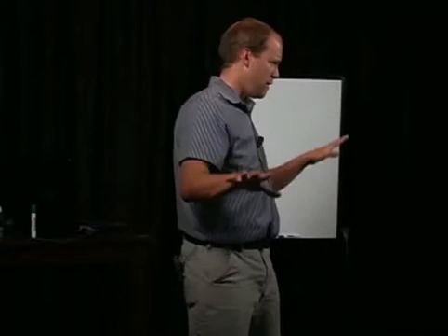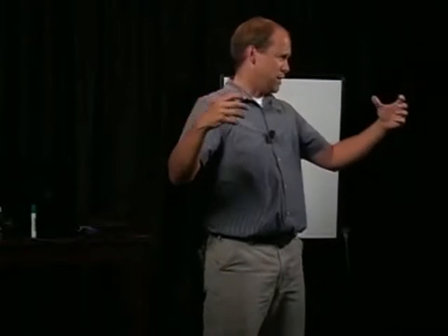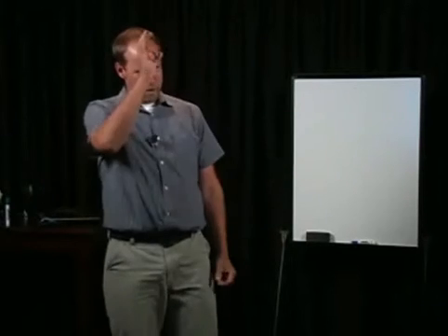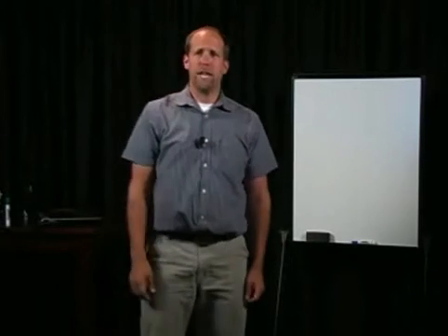Headlight. I used headlights and headlamps all the time to go into crawl spaces. That frees my hands. And when I went into the attic spaces, especially when there wasn't a whole lot of flooring or truss components to grab onto, and you're trying to balance yourself, a headlamp is really great. It frees your hands.